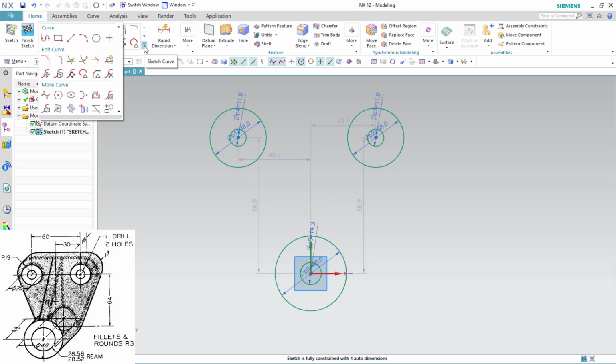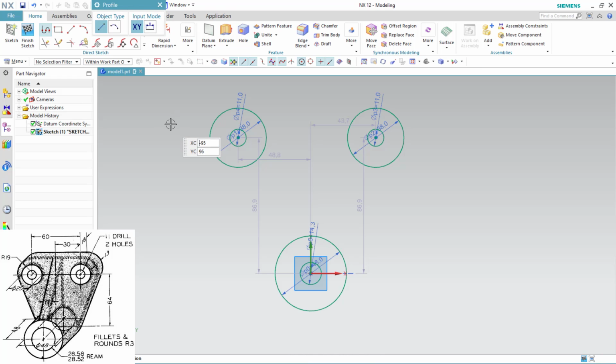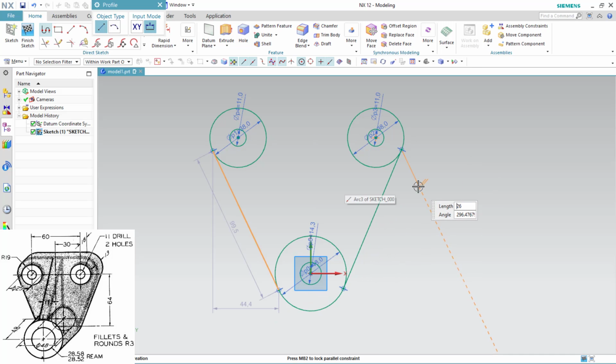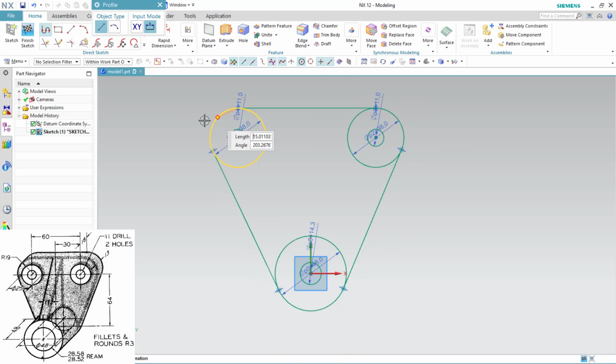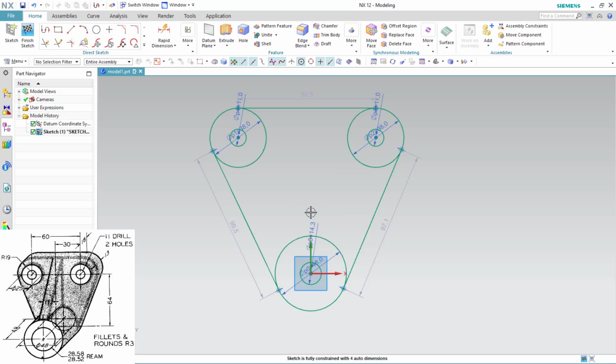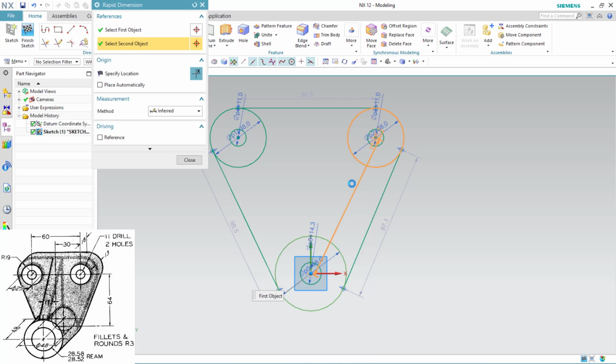Now I'll use the line tool. Instead of that, you can even use the profile. Yeah, but a line will work. Okay, profile is fine. Tangent, escape again, activate the Z, profile tool, and same thing. Just click anywhere you want. Once you get the tangents relation, you can just exit the sketch.